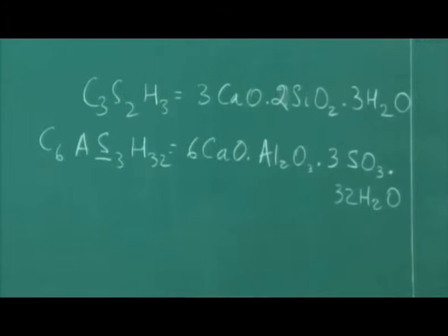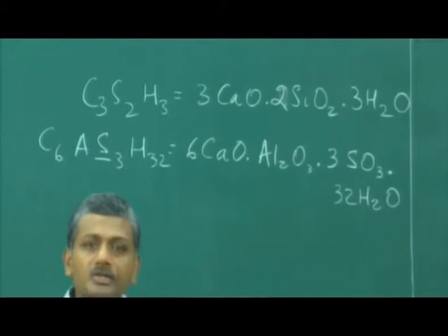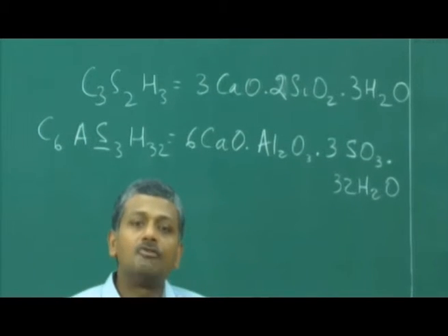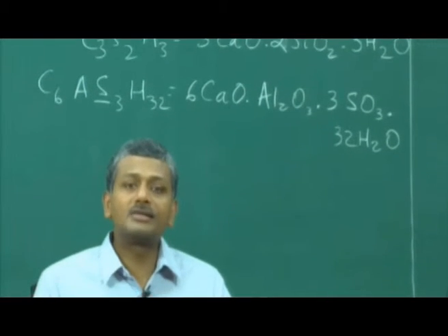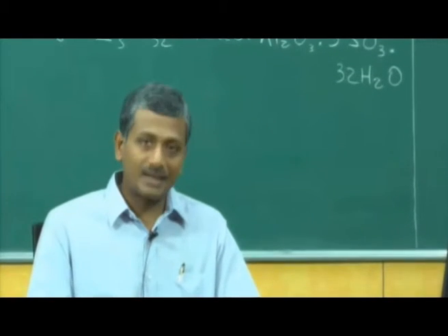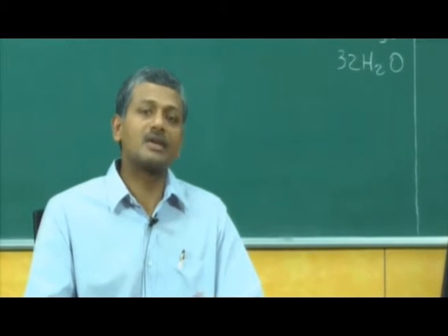That's your ettringite. And ettringite formation in fresh concrete is not really a problem, but when ettringite forms in hardened concrete, it is associated with an expansion which creates cracking in hardened concrete. That is what happens in the case of external sulfate attack.